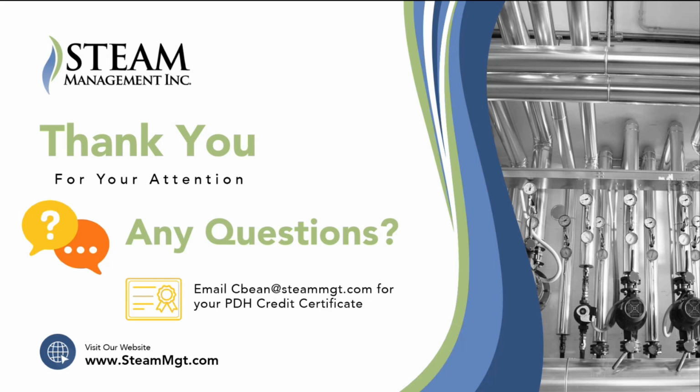Yeah, I've actually done a lot of paper manufacturing. But earlier this year we did a veneer mill where we did a steam control valve replacement. We replaced 14 control valves and upgraded their PLC programming in their steam system to help them protect their header pressure and some other things. It was a pretty neat project. And we have case studies on that on our website if you want to check that out.